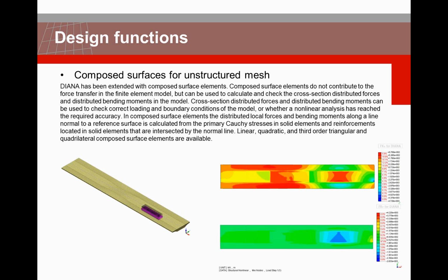If you use solid models, then in the design of structures you need to do the calculation of cross-section forces and cross-section bending moments. In Diana we offer the functionality of composed surfaces for that, but so far in combination with solid element models, the composed surfaces needed to be defined in a structured grid.